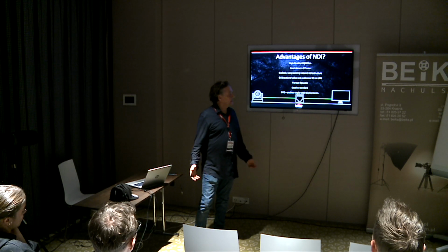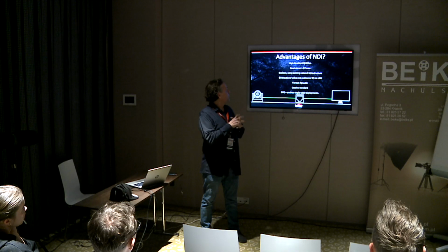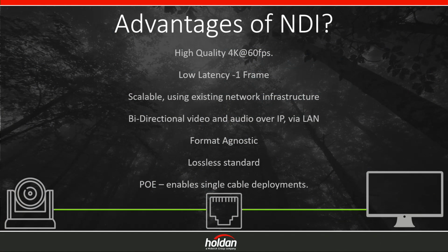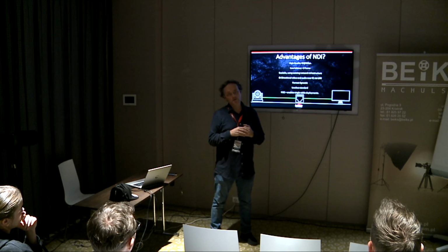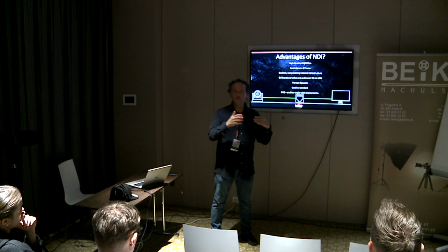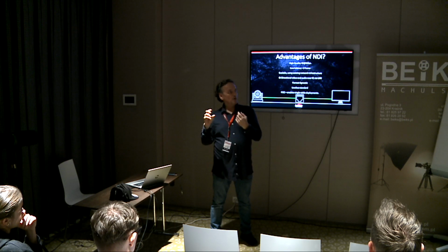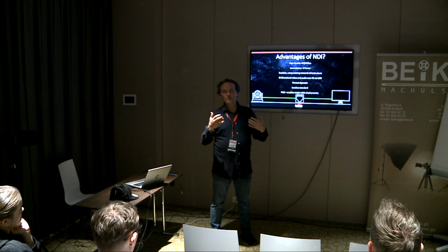So the advantage of NDI, like I said, I'm talking about full uncompressed NDI, and full uncompressed NDI has a low latency of just 1 frame, which means that it's very quick, and that's the big difference from NDI HX, which uses H.264 compression. Now, if you're familiar with compression, you lose picture quality, of course. It's a compressed image, so you can see banding and all kinds of other issues on your screen. But also, it's a compression where it analyzes the picture over a certain range of frames and then starts encoding and making predictions of parts of the image that are going to be repeated. That takes time to develop, and it takes frames to calculate before you can output it.